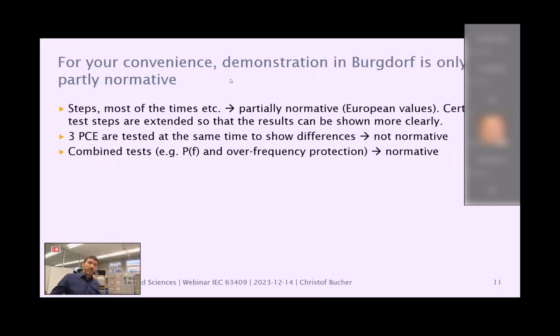As for the tests we do here in Burgdorf, first I have to say for your convenience, our demonstration is only partly normative. If we did normative tests, you should get your sleeping bag and wait for about a week or 2 weeks until we have performed only the protection tests. That's what we have discussed in the meeting just a few minutes before. And so therefore, we will shorten the tests quite a lot. On the other hand, fault ride-through takes only a few milliseconds to test. So there we have stretched certain tests so that you can actually see that something happens.